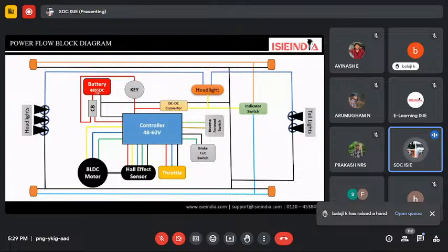So where we make a strong wire harness, we have to make a wire telematic in that sense. All of the components which are required, the basic essentials or for future extensions, we have to look at them and design the wire harness as per that only. Whatever components we are using for vehicle telematics, along with the power primary section, secondary sections, and the auxiliary components, we have to understand all of the inputs and outputs and connections. Then only can we design the wire harness of any vehicle, for a two-wheeler or a three-wheeler.